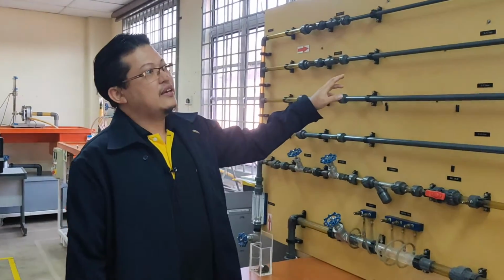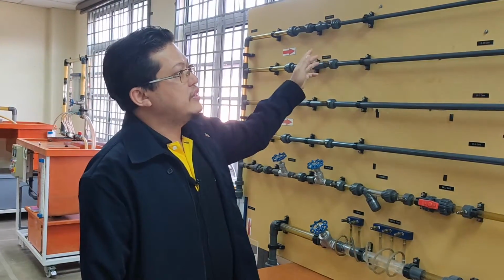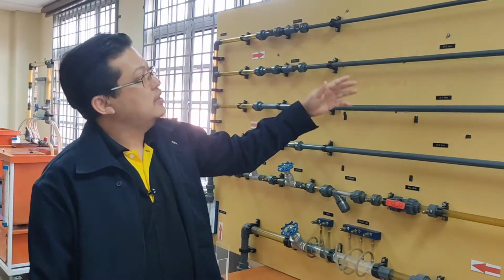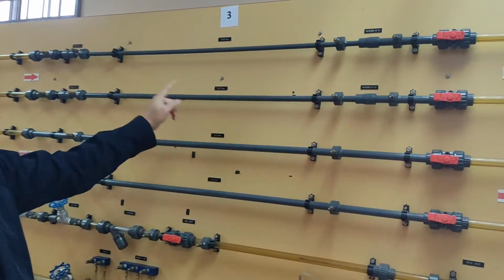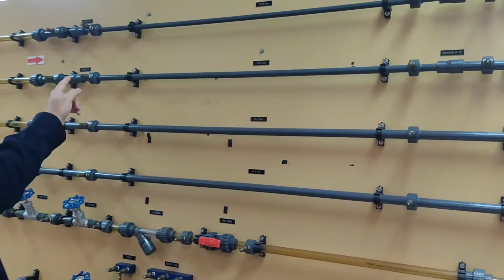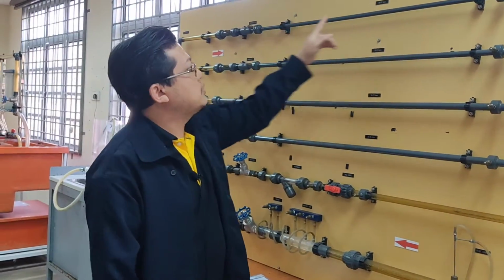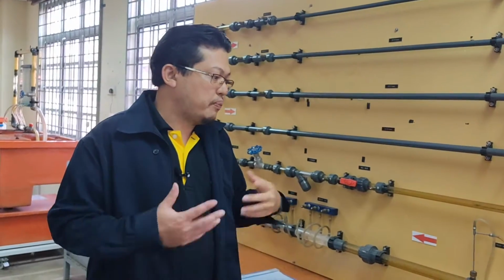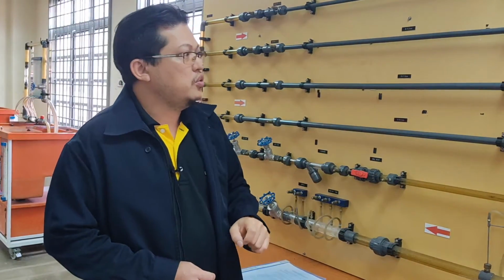Okay, the second task is when we want to measure the fluid friction inside the pipe using various pipe diameters. For example, the first one we have 10.3 mm, and then 13.5, 17 and 18 mm. So when we probe the digital pressure meter from this point to this point, we can calculate the pressure losses. So students also need to compare the experiment with the calculation. Students need to verify.